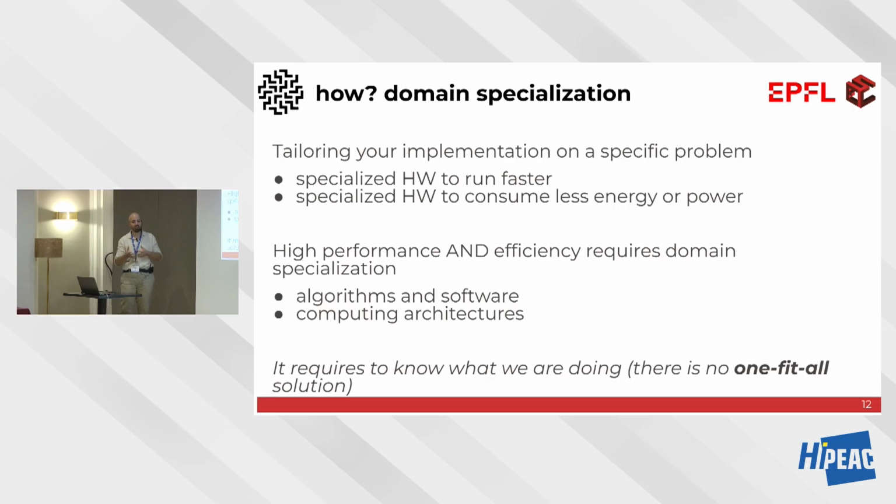If I add the custom instructions that is really good in doing the FFT, what I'm speeding up is FFT. So if I'm building a CPU that has to do crypto functions with hash and so on, the FFT is not useful. So in that case, it's specific to that domain. So for audio could be useful, and for security won't be useful, and vice versa, right?